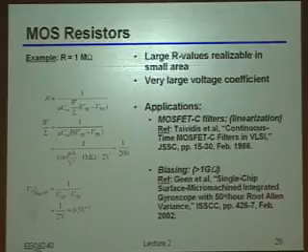Nobody can come up with even a single circuit where you just want a big resistor. You control it in feedback, for example. Okay, so I guess you paid attention to me last time when I said that feedback was almost always the answer. You could indeed control it in some sort of feedback. That's absolutely correct. That's one thing. But let's say I'm really lazy. I just want something really simple. Are there any cases where I just want a really big resistor and I don't care that much what the exact value is? Like pull up or pull down resistors?